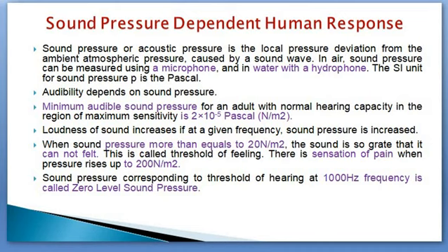Audibility again depends on the sound pressure. If for a particular instance sound pressure is very low, then for any frequency range sound is not audible to the human body. Minimum audible sound pressure for an adult with normal hearing capacity in the region of maximum sensitivity is 2 x 10^-5 pascals.